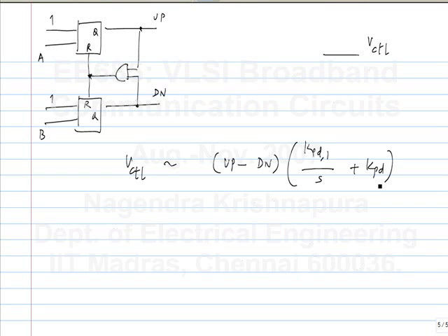In that PLL, we had disturbance because we did not. Yeah. I mean, how long will you average? There will always be disturbances, right? Maybe you will change the magnitude of it. Okay. So averaging is the same as inserting another pole. Okay. If you have a certain periodic disturbance at a frequency FF, and you pass that through a low pass filter whose pole is at some frequency much less than FF, it is like averaging that. Okay. That's what we have done here effectively.